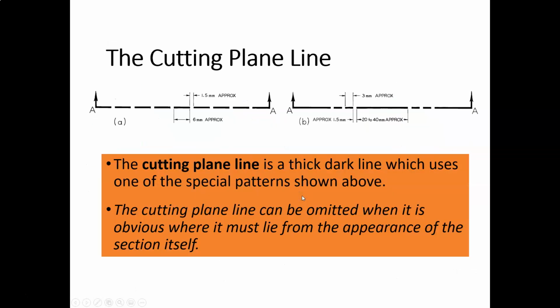All right, so let's talk a little bit about the cutting plane line. So this is how the cutting plane line is supposed to look. It's either large dashes, or it's an alternating long with two short dashes, long with two short dashes.